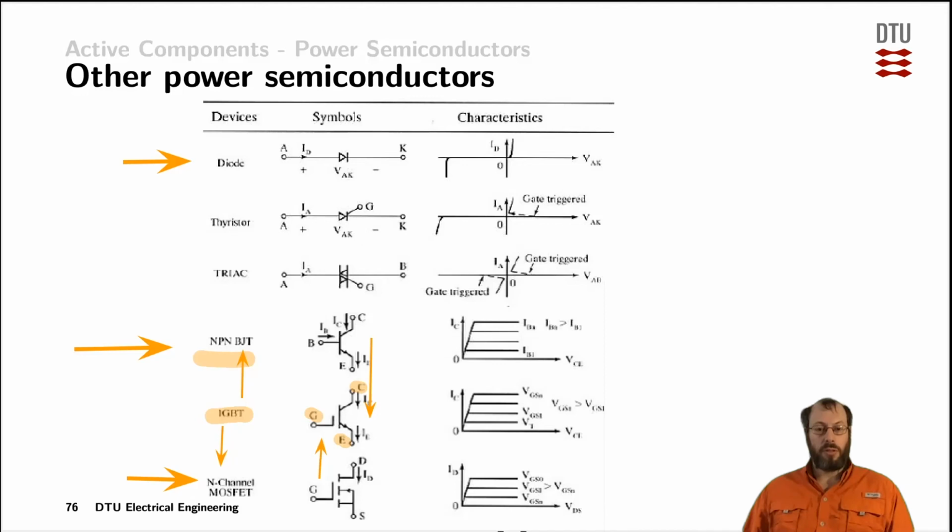Above that voltage range, and also far into the kiloamps range, we have triacs and thyristors. Thyristors have a similar forward characteristic like the MOSFETs and IGBTs, but their characteristics can be shifted along the x-axis. In the reverse range, they behave very similar to diodes. So compared to MOSFETs, they can actually also block negative voltages.